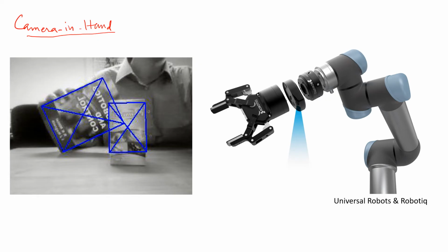So in that case, the robot is not going to hinder the field of view of the camera, and that is going to greatly help understand the situation. But there is an associated problem with that, and that is when the robot is going to get closer to any object to be picked up, the object is going to grow bigger. And when the robot is going to have a rotation or reorientation, then obviously the orientation of the object is going to change. So growing something bigger as you get closer to it is going to be another problem, and reorientation is going to be another associated problem when you opt for the camera in hand paradigm. So as you hear that there is no free lunch, this is kind of a similar situation.